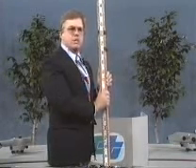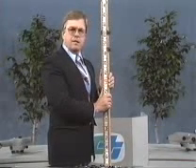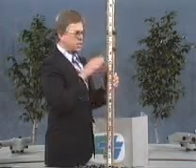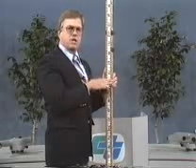So when you pick the rod up and move it to another position and set it down, even though it might not be at the same elevation as the benchmark, you can then directly read the elevation on the rod.